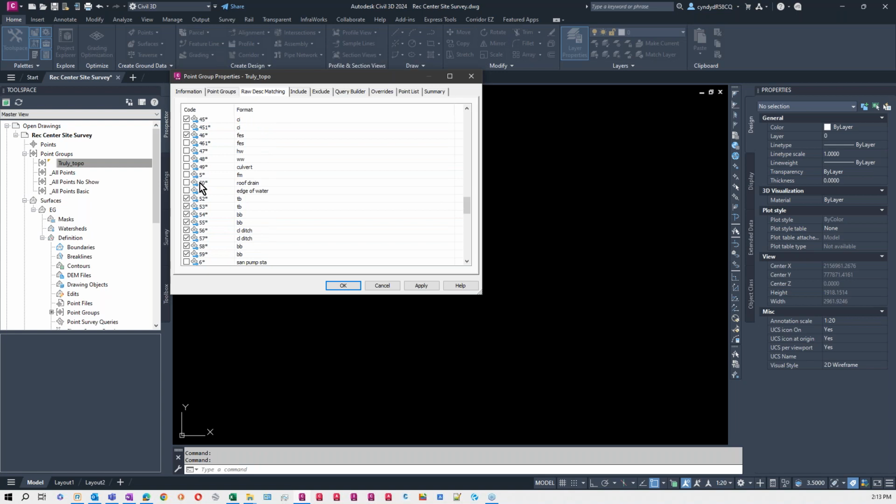Not all points that a surveyor picks up represent a surface. The only point representing a surface is one that is taken off of a surface. Sometimes a surveyor collects things and the instrument may not be sitting on the ground. For instance, a light pole, it could be sitting up on the pedestal. For a fire hydrant, it could be sitting right on top of the fire hydrant. For a building corner, it could be up on the cornice. Or even for manholes, the manhole could be recessed in the ground, but it's not a true low point on the side. Since that's just a really dense 2-foot diameter low section, you don't really want to include that in your surface.